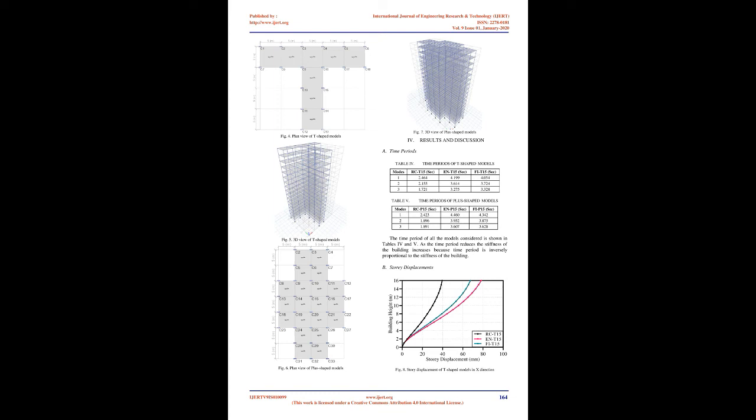Mohammed Sabath K. [5] presented a paper on the seismic analysis of irregular composite structures with shear connectors. The study is carried out on a plan irregular structure of a medium-rise 10-storey building. Modeling and analysis were done to estimate the behavior of the shear connector and compared with the RCC structure. It was found that storey displacement is higher in the composite structure. The composite structure has reduced stiffness, which makes the structure flexible. Storey drifts are larger in the composite structure than RCC. Axial forces are reduced by nearly 50% in composite structures.